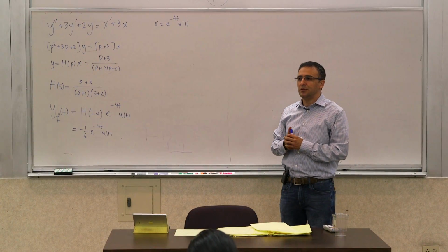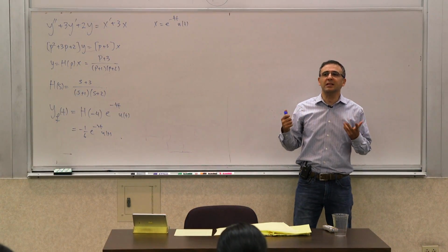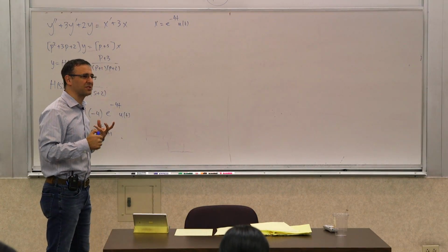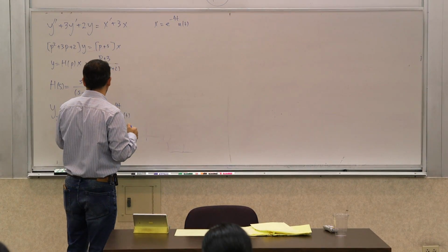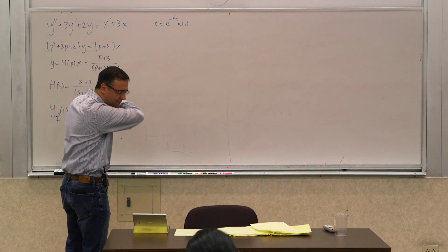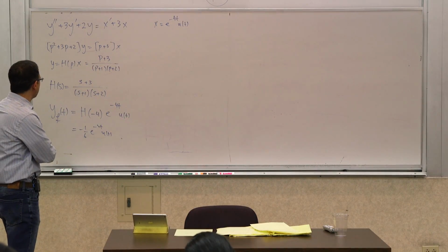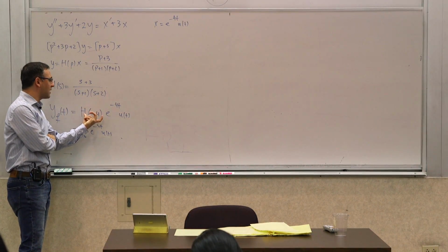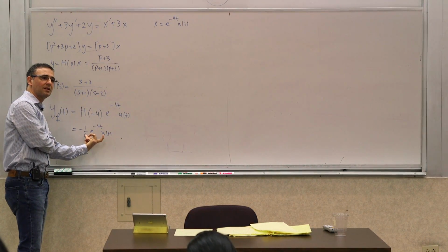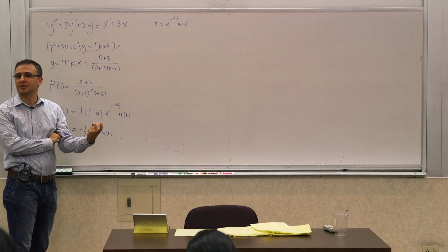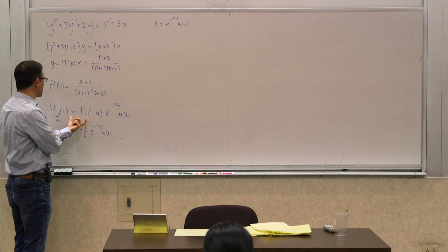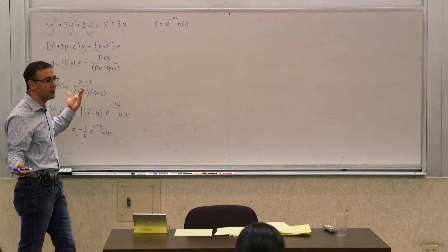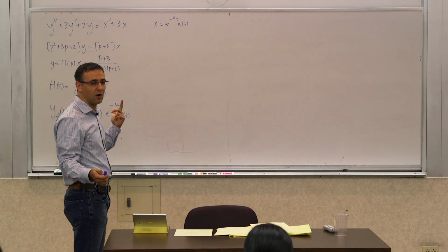So you can see the strength of the system function, right? Sometimes it's called the transfer function, but the transfer function is a more special case. The significance of a system function is that it allows you to directly find what the forced response is for different frequencies. So it captures the forced response of the system at all frequencies. If you look at this function, you know what its forced response is to all frequencies. Almost all frequencies.